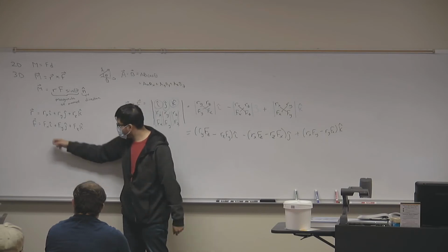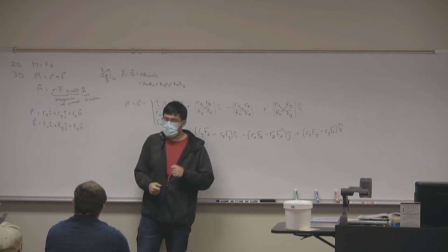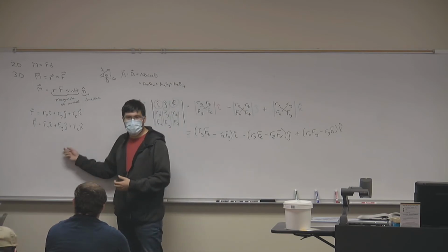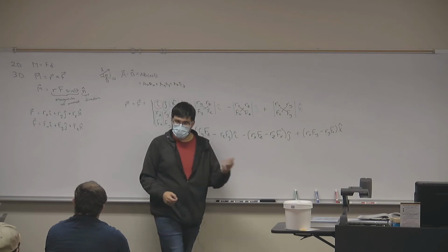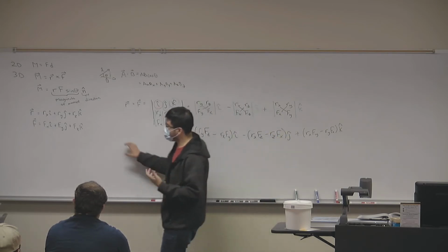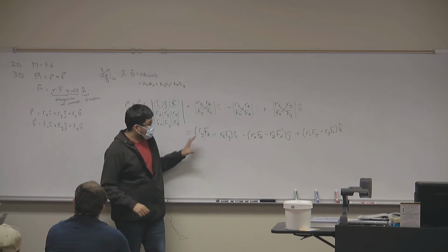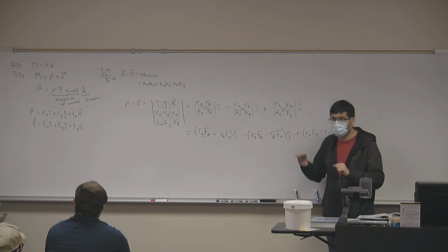Fx squared plus Fy squared plus Fz squared, and then take the square root. Likewise, can you find the direction of a force? In 2D space, can you find the direction? Yes. Inverse tangent of y component over x component. We can do the same thing in 3D space. It's the same concept. The vectors are still the same. It's still vector theory here.